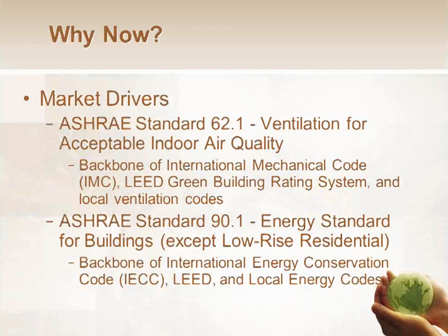The main drivers on why these are becoming more popular are because of the standards that have changed over the past decade, and these standards feed into the codes. So there's two main standards at play. One is ASHRAE Standard 62.1, which is the commercial ventilation standard. Amongst other things, this standard specifies how much outside air needs to be brought into a commercial building, and there's tables in there that dictate how much air is brought in for different types of buildings.